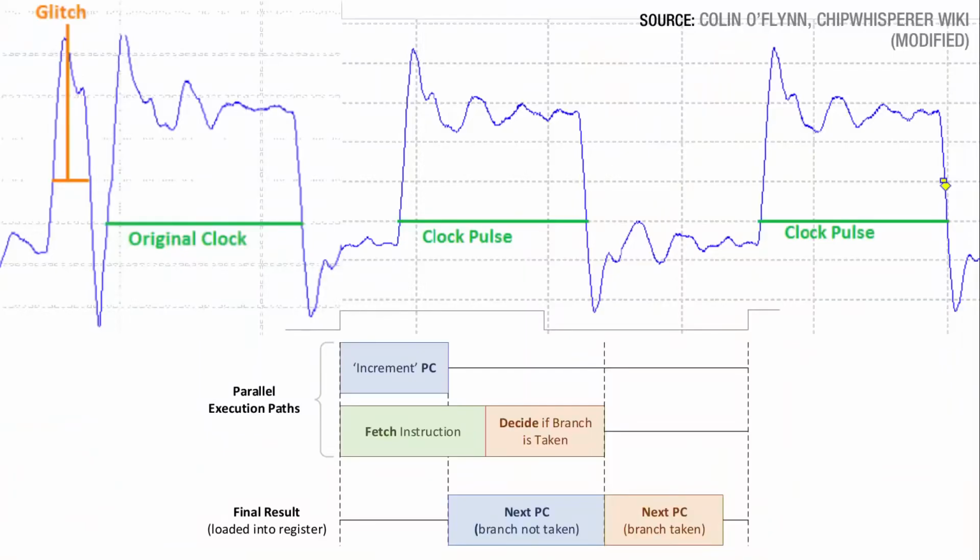Okay. What you have is these nice clock pulses that you can see on the slides. I think the way a lot of people visualize what happens inside a processor when the clock signal comes on is like everything happens as soon as that clock pulse happens. But realistically, those things happen in stages. First of all, maybe we increment the program counter, and then we decode the instruction that we're pointing to, and then we work out what that's going to do, is it an add?